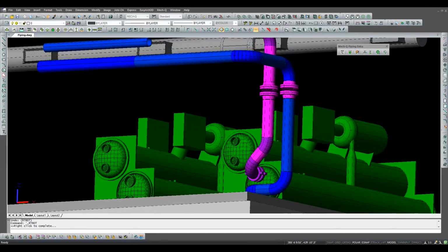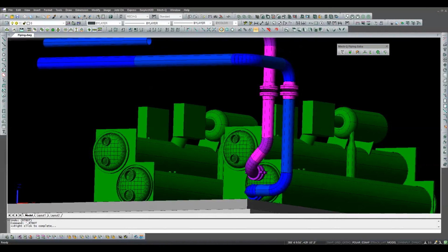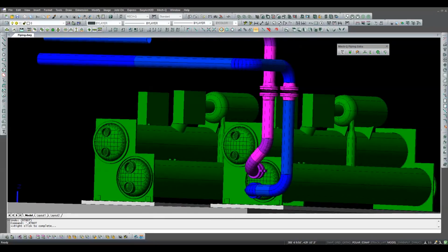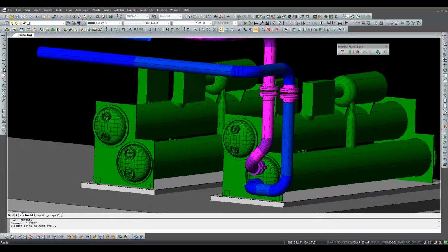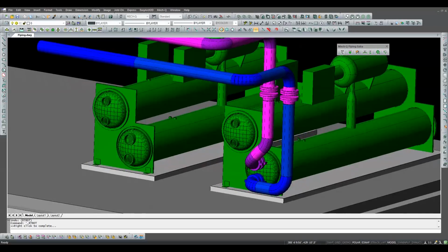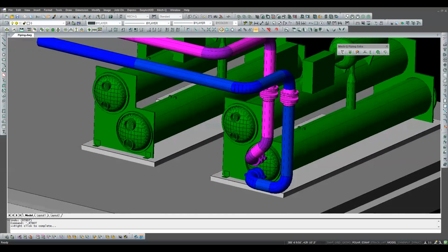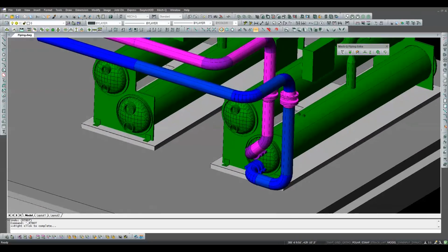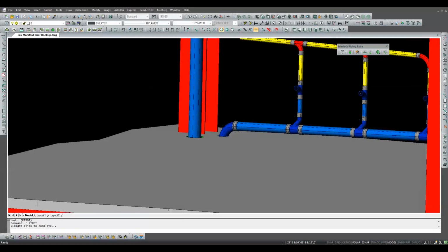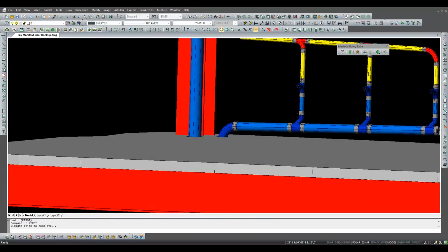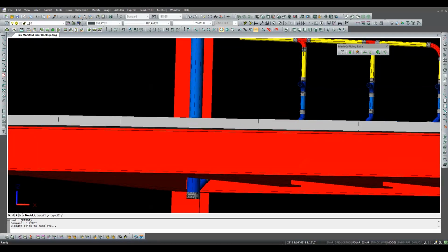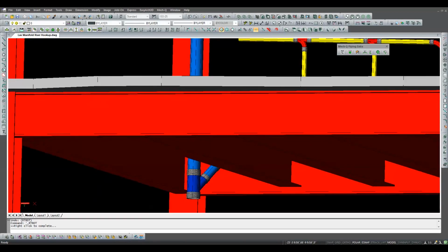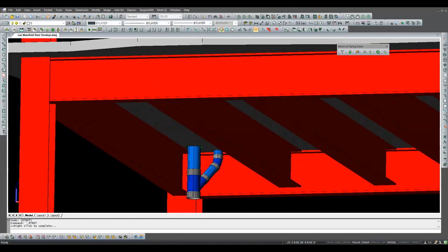All that remains is to install and adjust the remaining pipe and elbows, and this portion of the chiller piping is complete and ready for spooling. Using the power of 3D CAD, all of this was accomplished without any construction lines or a single calculation. Now let's look at a pair of non-90-degree fittings and see what effect fitting rotation has on the slide routine and proper fitting placement. Here we see a typical lav header hookup.